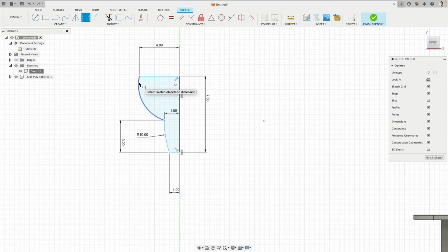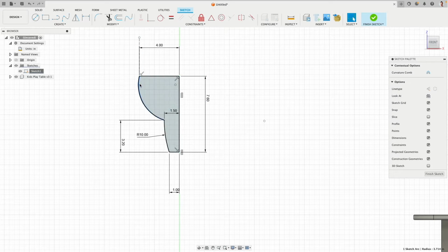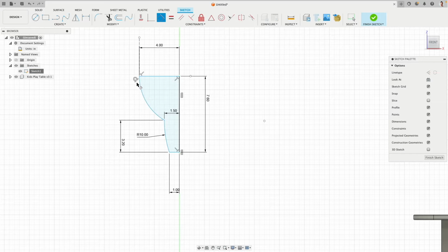I would like this arc to terminate at 90 degrees on this line. Little trick, I will just create a helper line. Okay, this line is perpendicular to this line, so that's good. Otherwise, I make this 90 degrees. This can be simply a construction line, and then the arc to this line is going to be tangent, and that forces it in. Beautiful.